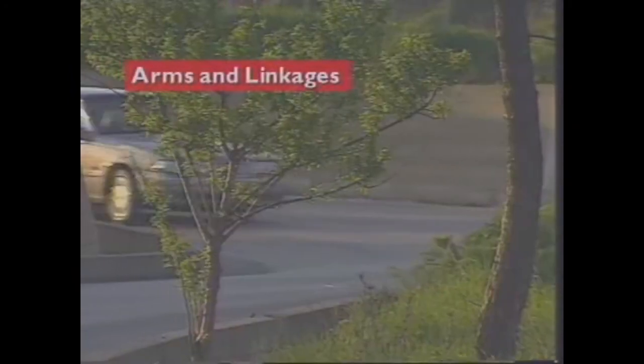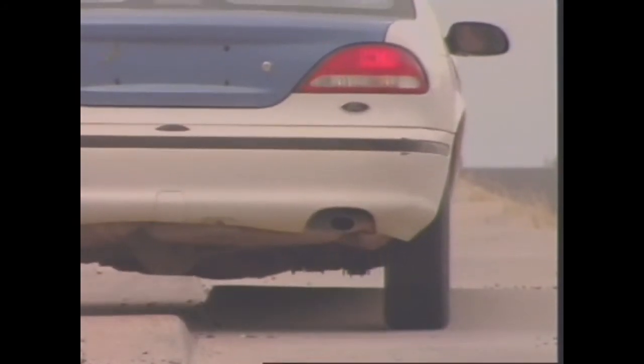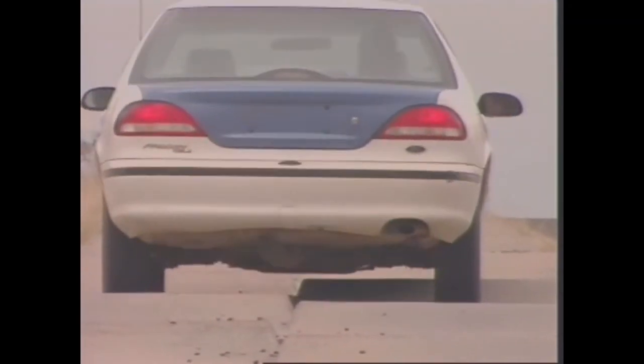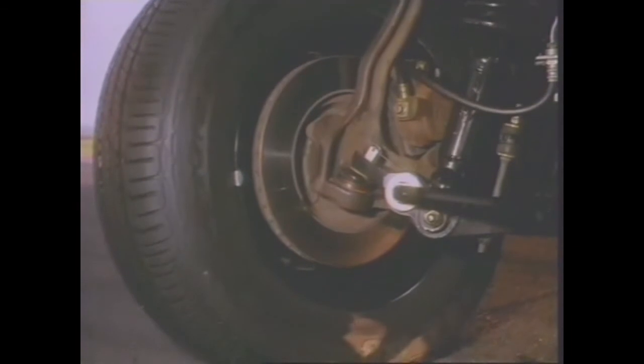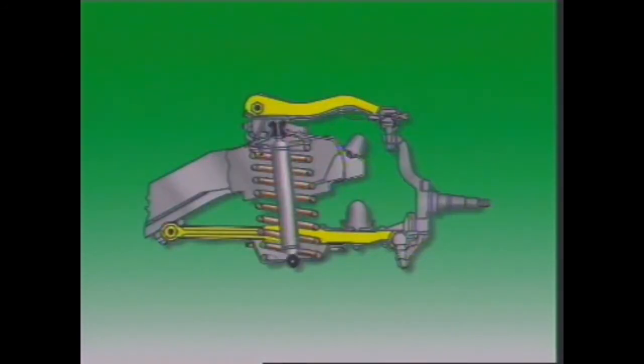This section examines suspension, steering arms and linkages. The major components of the suspension system must be firmly located to withstand the forces that occur in normal operation. Control arms fasten a component like a rear axle assembly to the vehicle body, while allowing it to move as it needs to. Similarly with a steering knuckle. The arms must be strong enough to withstand the forces due to normal operation, but light enough to minimize the vehicle's unsprung mass. The front suspension can have 1 or 2 control arms.